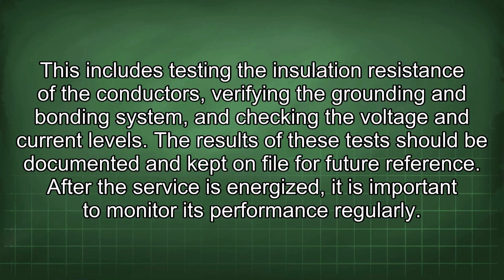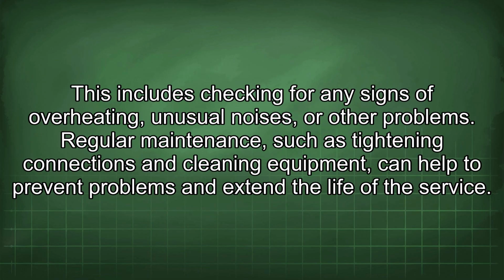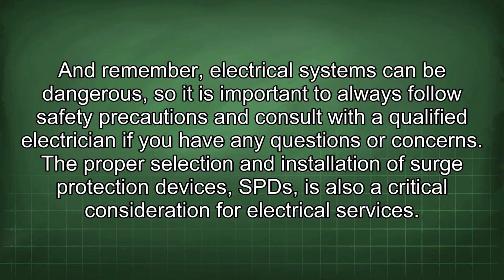After the service is energized, it is important to monitor its performance regularly. This includes checking for any signs of overheating, unusual noises, or other problems. Regular maintenance, such as tightening connections and cleaning equipment, can help to prevent problems and extend the life of the service. And remember, electrical systems can be dangerous, so it is important to always follow safety precautions and consult with a qualified electrician if you have any questions or concerns.